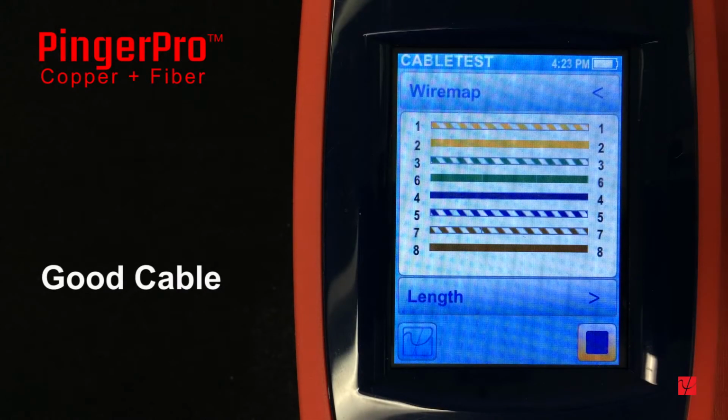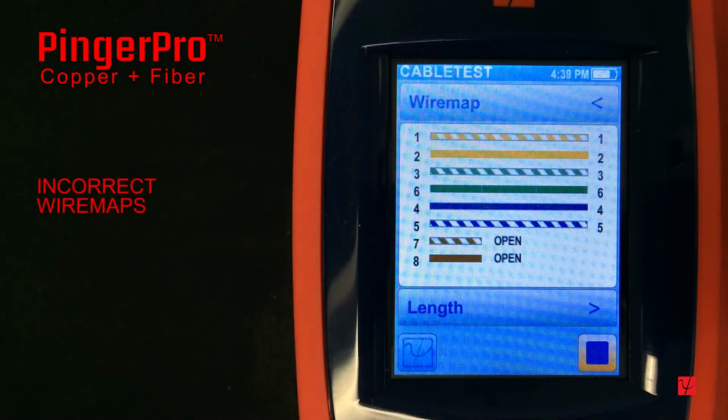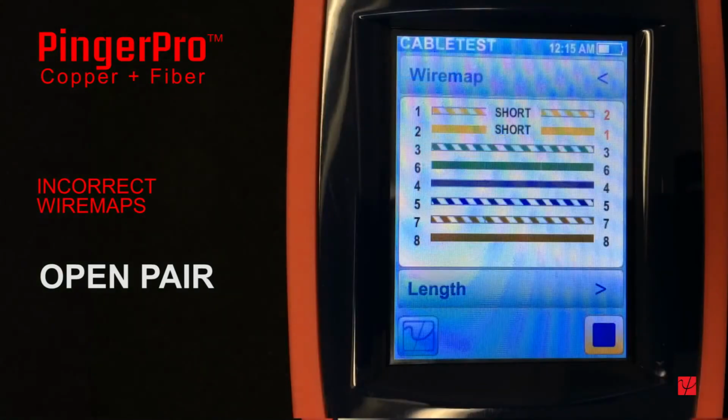When terminating an end of a network cable, it is easy to miswire a plug or jack, which can cause a device not to work when installed or reduce device performance due to loss or corruption of packets. Here are some examples of incorrect wire maps that the PingerPro can detect. An open pair occurs when a wire is not physically connected or the cable has been damaged with one or more wires cut.